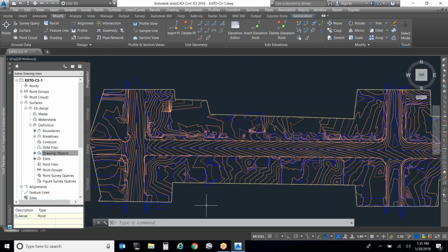Basically, I'm saying maybe between the paint marks and the potholes, you might start getting enough survey level points, grade where it's very useful to your project. Potholes are like the surface shot at that utility. When we know where it is, it's the most important data. That's the point you're using to set your pipe, exactly, once you have pothole data. So that becomes part of your model to set your pipe.